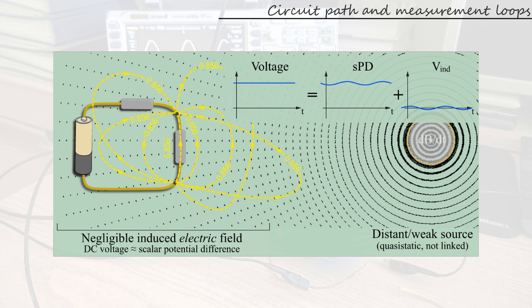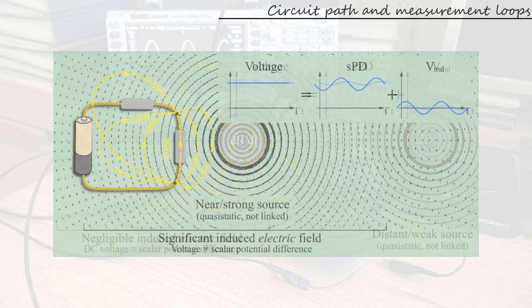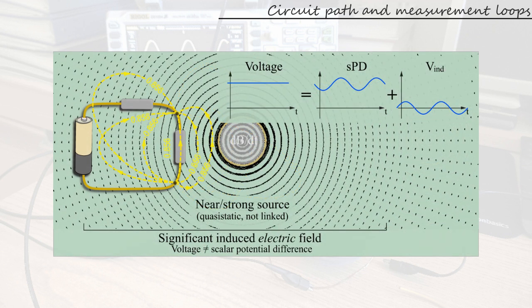As long as it is not linked by the circuit path, it is not particularly difficult to consider voltage as a single-valued quantity. All we need to do is to avoid cutting through or going around the external dB/dt region with our yellow paths.